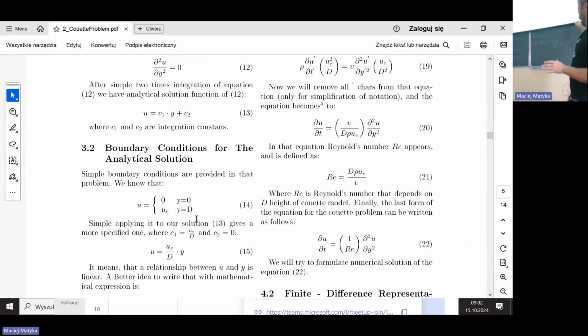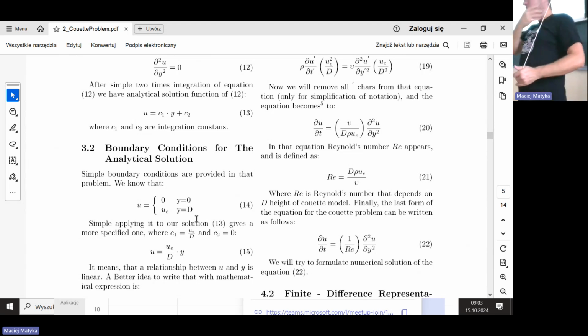Again, highly viscous fluids are honey and oil. Highly viscous means low Reynolds. Low Reynolds flows are much simpler to solve numerically, and much simpler to solve analytically. But high Reynolds number flows are very hard. These are flows where turbulent effects appear. The turbulent effects appear because the numerator takes over, and the whole dynamics depends on the momentum of the fluid, or the advective term. Everything flows everywhere, and it's very, very hard.